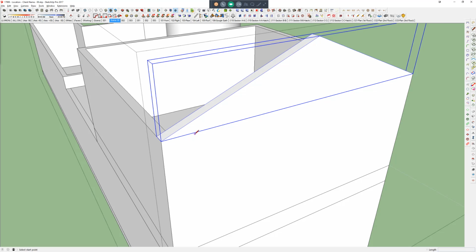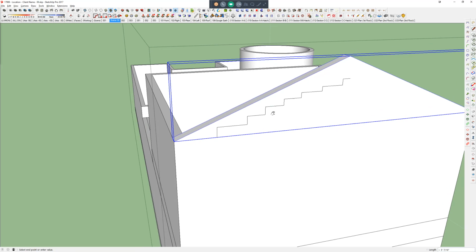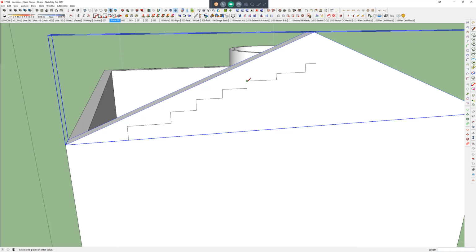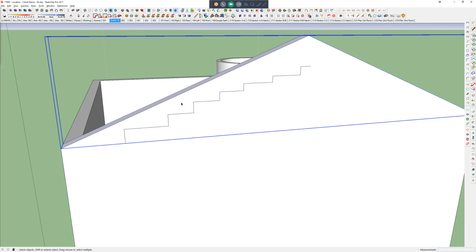Although I guess technically they would build a block wall like this, if that makes sense. Yeah, you know, they would basically build as much block as they could in a triangle, so that this distance would be minimum, you know, 8 to 12 inches, whatever your beam is designated at. And then they would pour all of this.